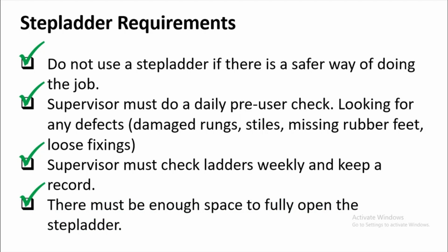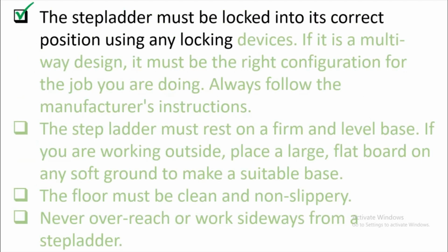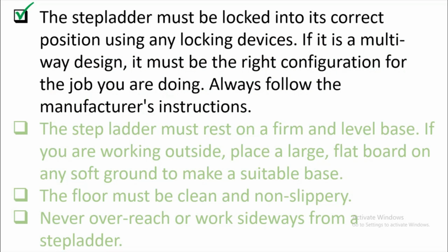There must be enough space to fully open the step ladders. Okay, so it is very important that before you use the step ladder, you fully open it and lock it so that it will be stable. So you need enough space for the step ladder. The step ladder must be locked into its correct position using any locking devices intended for it. If it is a multi-way design, it must be in the right configuration for the job you are doing.